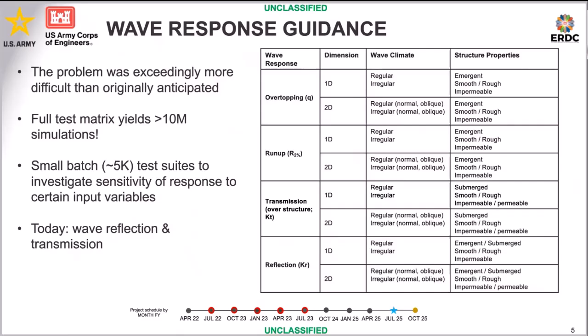We wanted to look at structure properties, like its freeboard, the side slope of the trapezoid, its crest width, its crest height, and its roughness, because that is like the gamma F in the overtopping and run-up equations, for example. How does that relate to the CD in FunWave? We wanted to get to that.